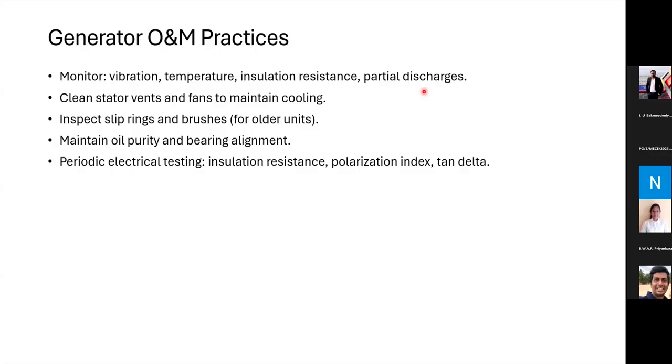Partial discharges can be detected via sound, by observing the voltage waveform, and visibly as well. We need to detect whether partial discharges are occurring in the generator, and if so, take necessary repair action, not just maintenance, to bring it back into a proper operating condition.